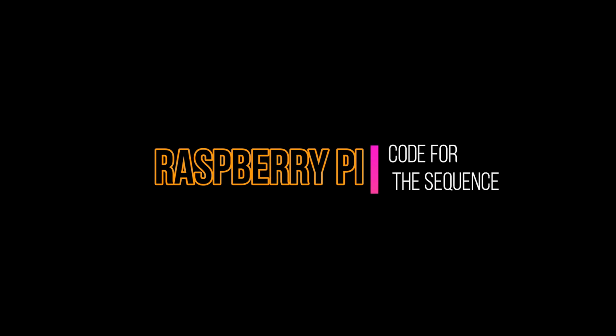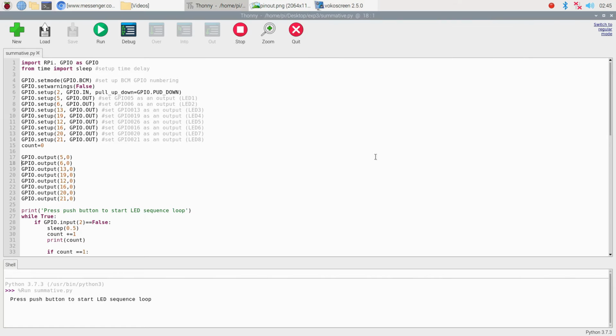So here is the Raspberry Pi code for this assessment, wherein we will be utilizing two sequences in a loop. The first line, import RPi.GPIO as GPIO, is the general purpose input-output. Line 2, from time import sleep, is the setup for the time delay. Next is GPIO.setmode(GPIO.BCM), the setup for BCM GPIO numbering. Then we set GPIO.setwarnings to False.